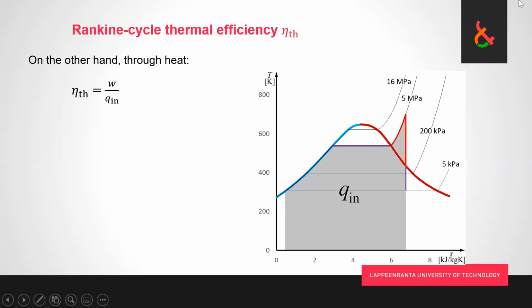the heat basically is the integral from the beginning point to the end point of T dS. So basically that means that if we are right here in this corner, we're at the point where heat input in the boiler begins. And then we start to heat the work fluid until we get to the point where the curve actually meets the saturated liquid water curve. So it looks like we are going on the curve. And this is just because all the changes in liquid form show very, very tiny temperature variations here.